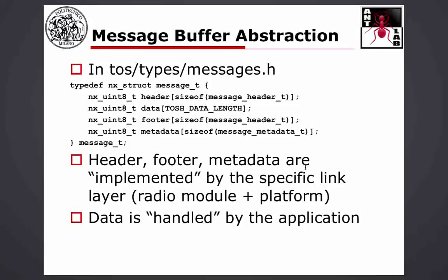The only part which is interesting is that header, footer, and metadata, which are, let's say, the parts which do not contain user data but contain protocol data, are actually implemented by the particular hardware that you are using. So on this kind of hardware, we have the CC2420 radio chip, and TinyOS has specific components for that.